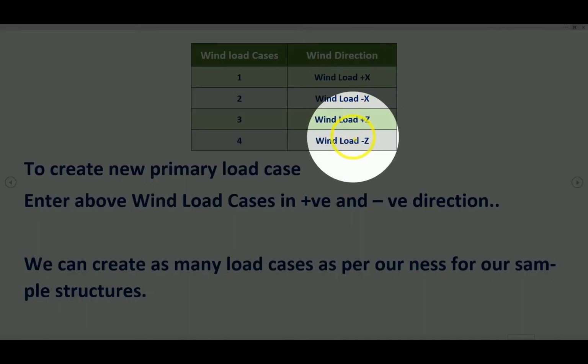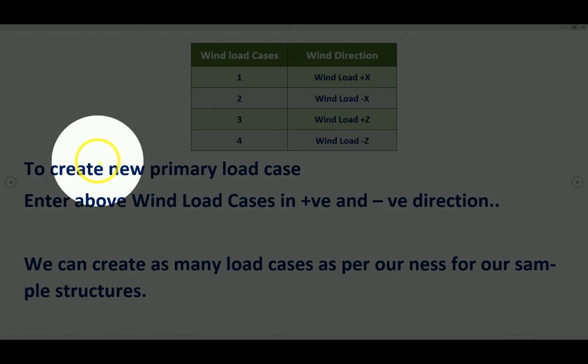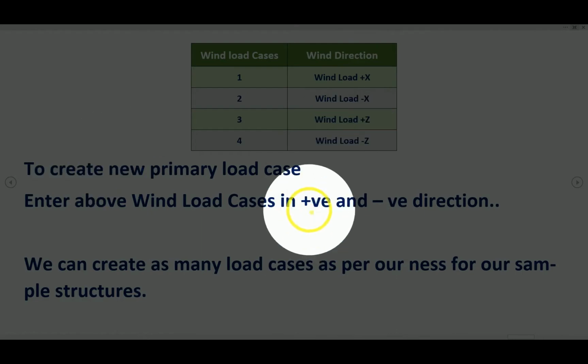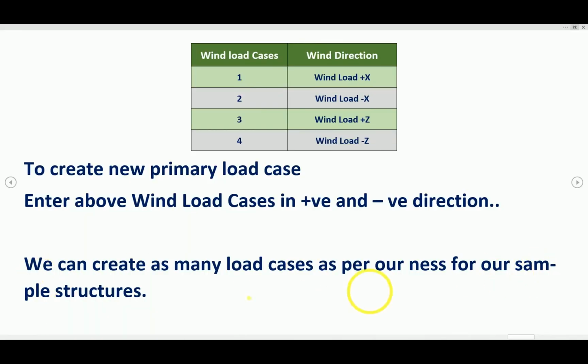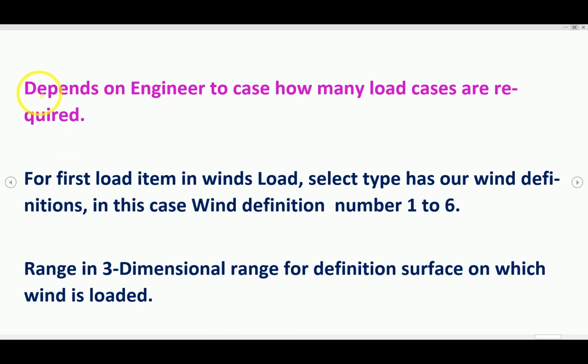Now we will enter our wind cases. We can create as many load cases as per our requirement, and that depends on the engineer to decide how many load cases are required. It's his responsibility to check the definitions are proper and loads are calculated and applied.